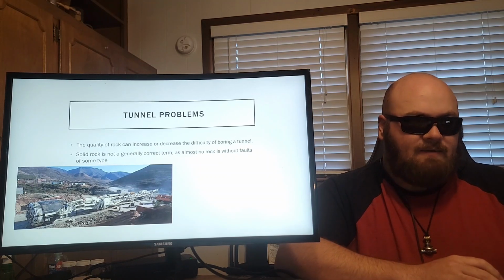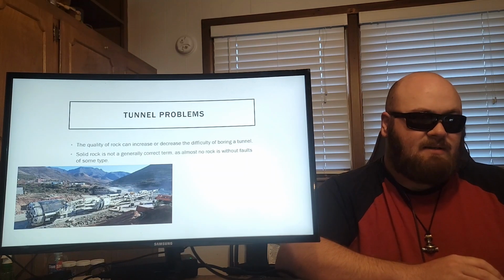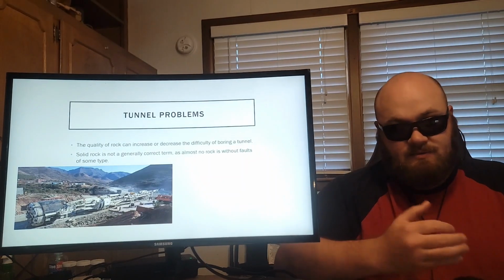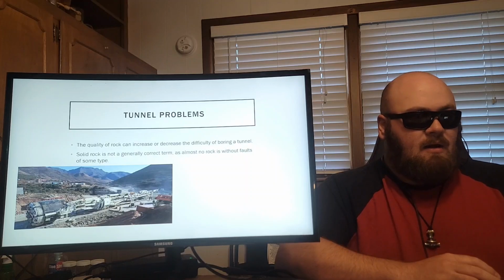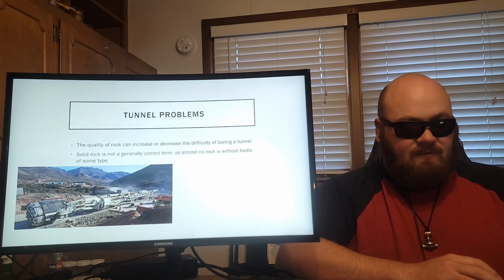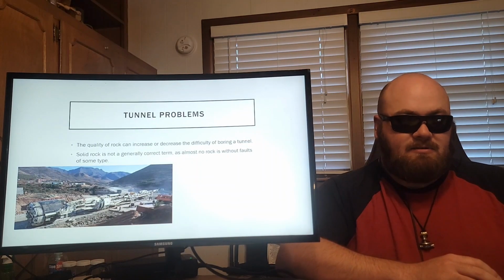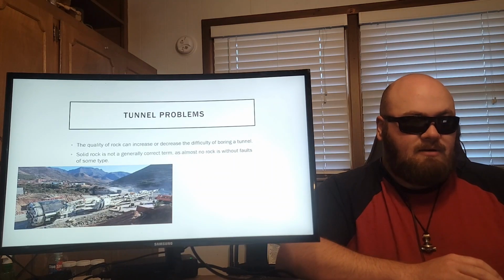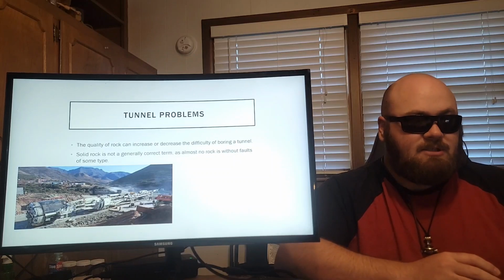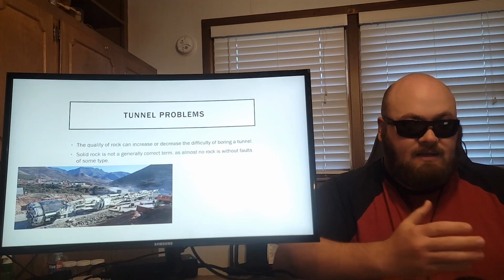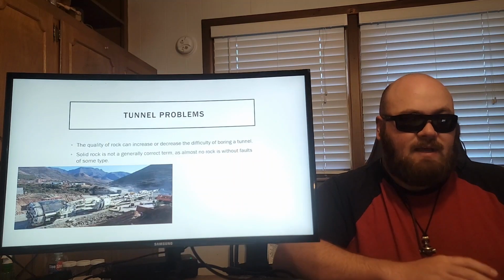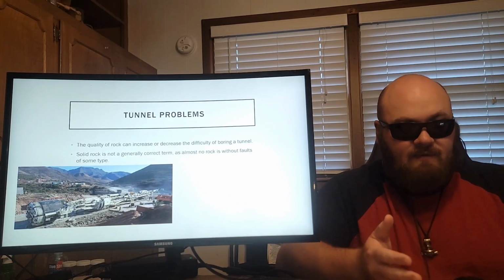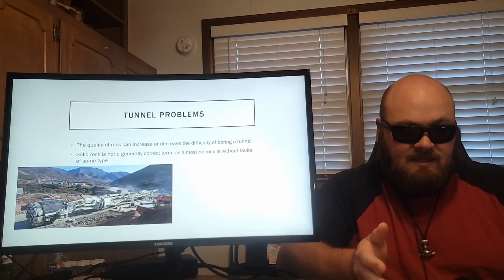Tunnel boring, while not having to deal with underground stresses that can cause seismic activity like dams storing water, because you're not really going to introduce more weight through a tunnel construction, you will have different issues that are caused by the geological structure of a tunnel. A quote from Jared Coleman et al. quickly emphasizes this, stating that it is difficult for the machines to cut through weathered, sheared, and highly jointed rock, showing how even small changes and imperfections in the rock itself can change the timeline of a boring project if not sufficiently planned for alongside significant testing.